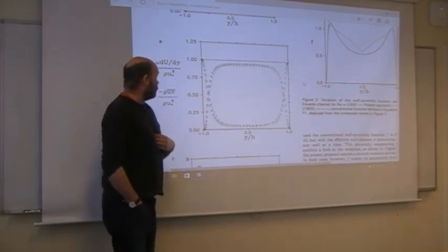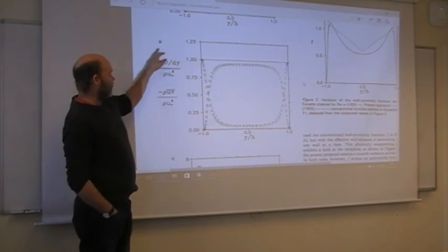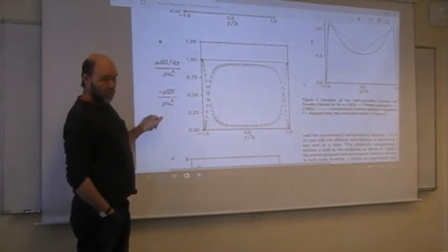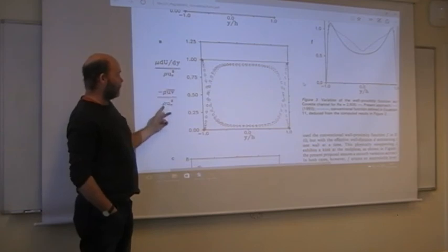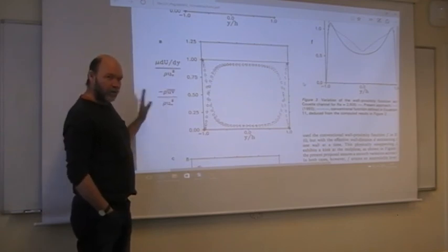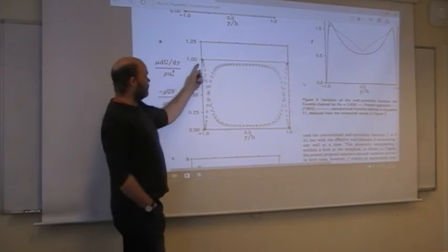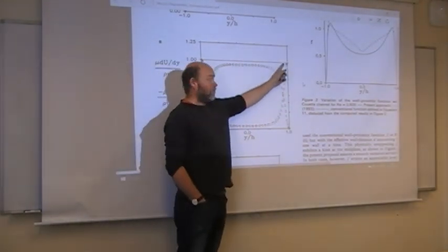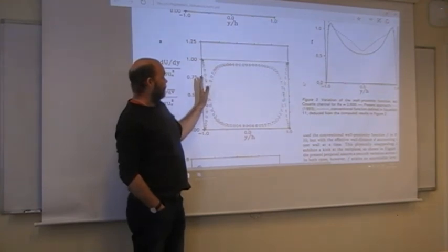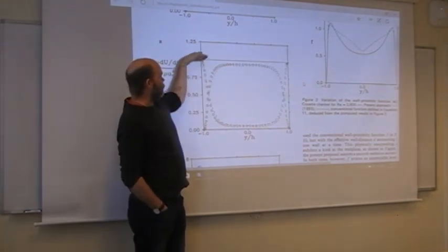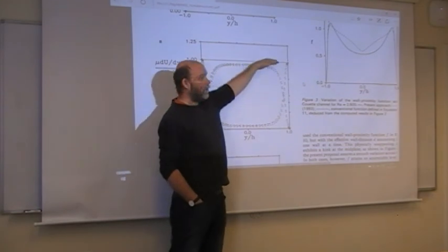So you plot the total shear, both the viscous and the Reynolds shear stress, and because you know the sum of them is going to be constant, this straight line here is not just a line drawn in the figure. It's actually the sum of these terms, and then you check afterwards, is this a straight line or not?